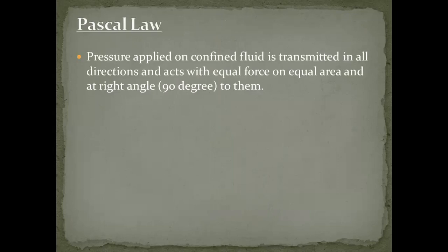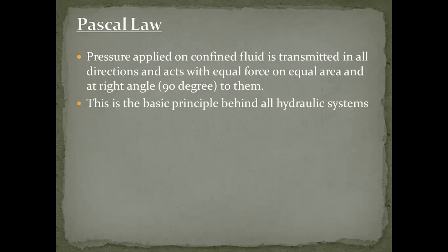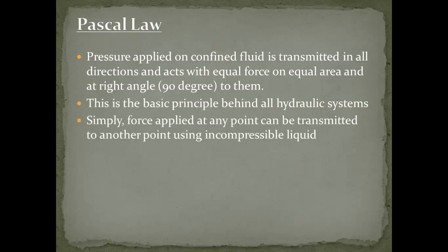So basically, the whole branch of hydraulics is dependent upon the Pascal law. Pascal law states that when pressure is applied on a confined liquid, the pressure is transmitted in all directions and acts with equal force on equal area at right angles to them. This is the basic principle behind all hydraulic systems. Simply, force applied at any point over the liquid can be transmitted to another point using the incompressible liquid.